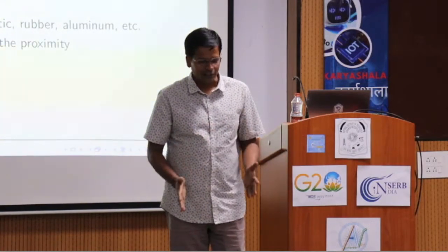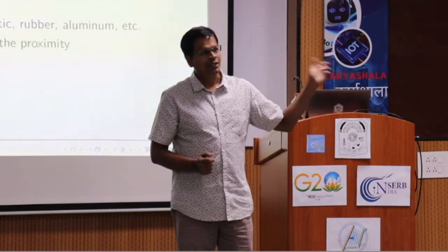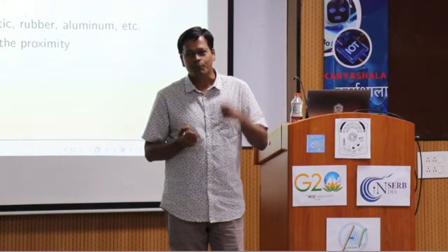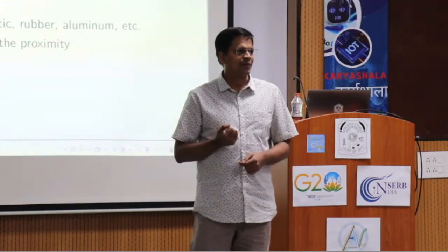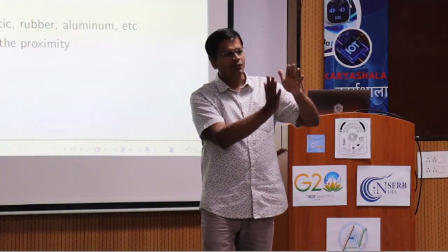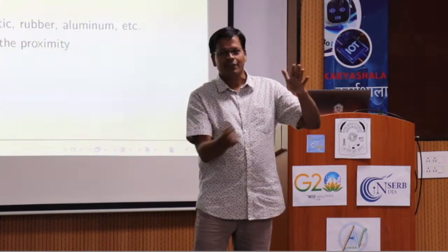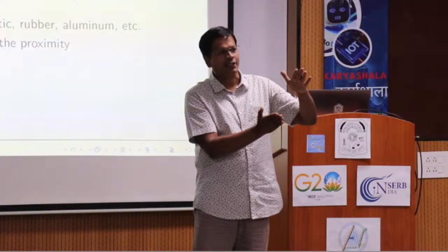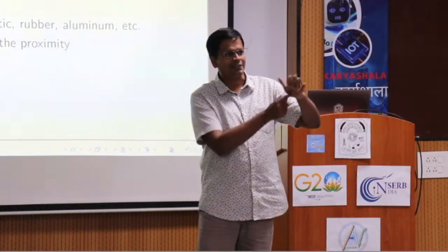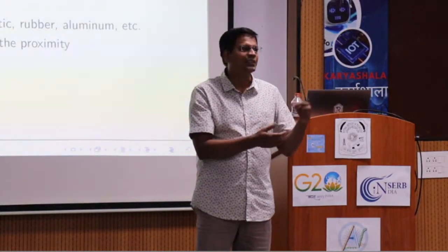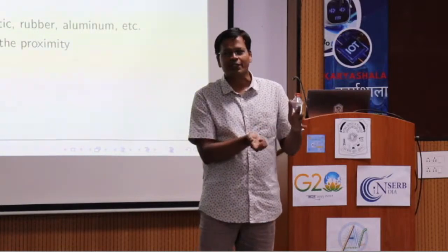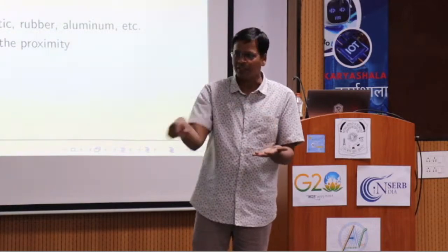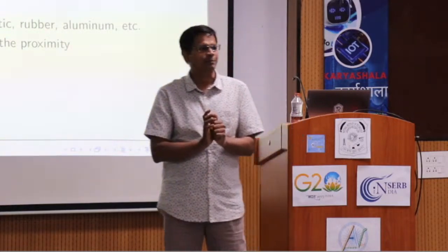Your robot rotation with respect to universal frame is calibrated and calculated before you put your robot to the use. Once you mount the tools, your frame has changed. If it is a welding tool, it is somewhere over here. If it is a clipper, it is somewhere over here. Right? So frame change is calibrated. That is known as TCP calibration, tool center point calibration. You do some sort of identification experiments to find out those frames.